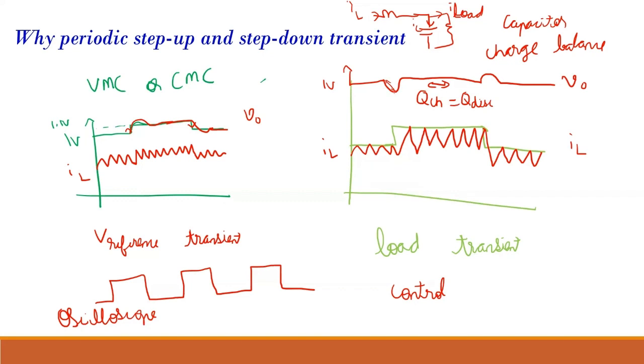And from which time to which time are you considering it charging and discharging? When the voltage is falling, it is a discharging process. That time the amount it is discharged is more than the amount of charge which is stored in it. While when it starts rising, then the amount of charge which is given in the input is more than the amount of charge which is discharged from the capacitor.